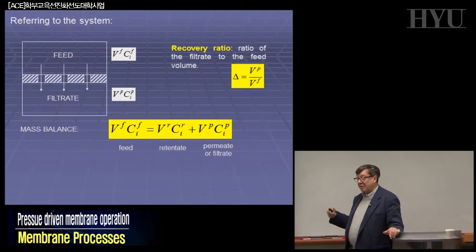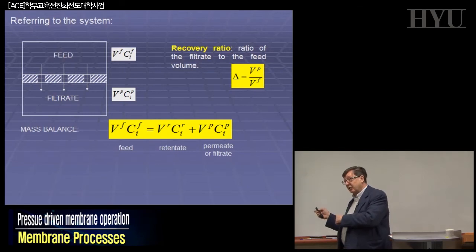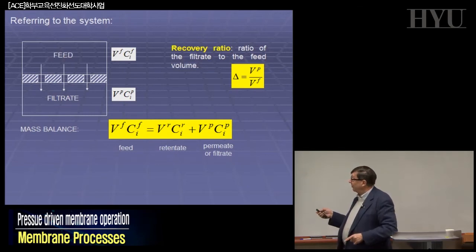In normal distillation, MSF, MED, you have 20, 10, 30 at most recovery ratio. Having 50, 60 or more if possible, and we will discuss membrane distillation, because in membrane distillation the recovery factor can be 95%. What does it mean?